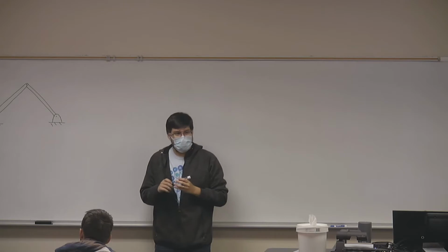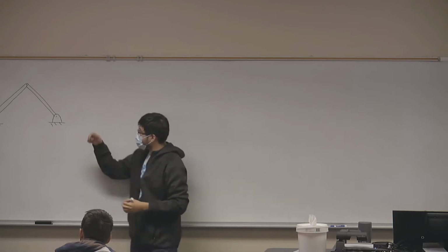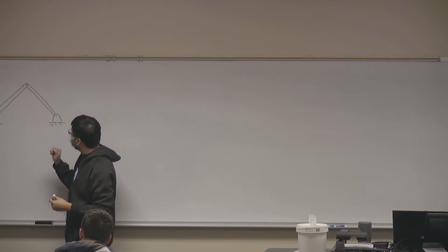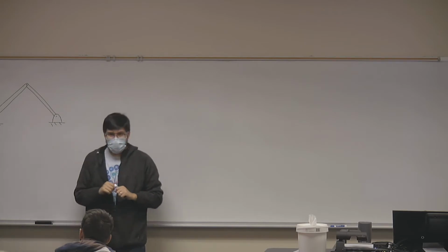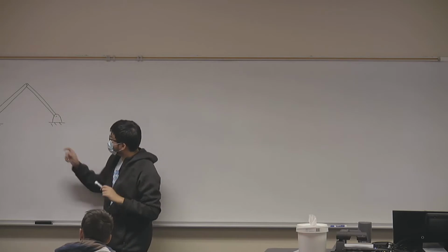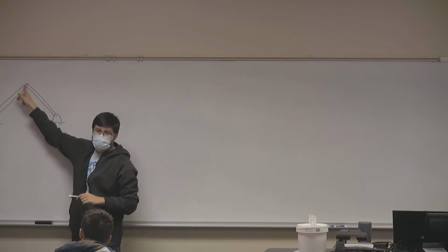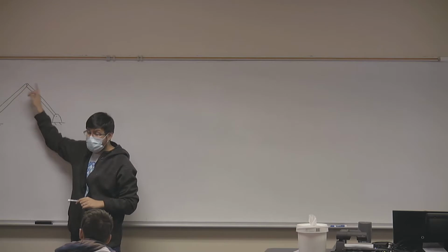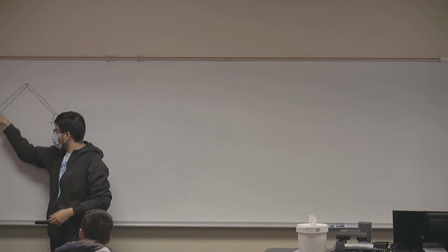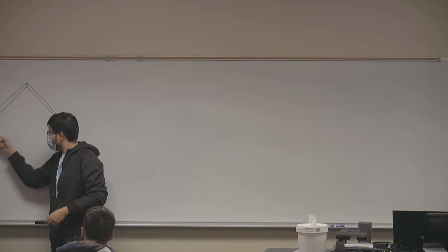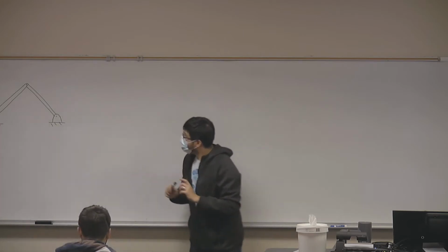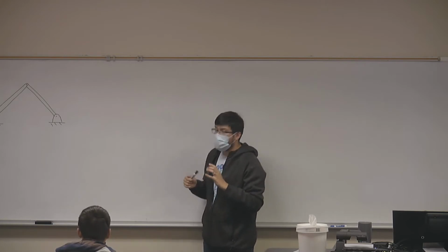Looking at this system, where we have a structure that consists of two trusses supported by a hinge and a roller, what movement is possible right now? Just looking at the system the way it is. Remember, we treat these connections as if they were hinges, okay? And remember that hinges really only prevent rotation. So what we have here is a hinge, sort of, but on a roller, so they can also move linearly. So right now, what movement is allowed or is possible in this system?